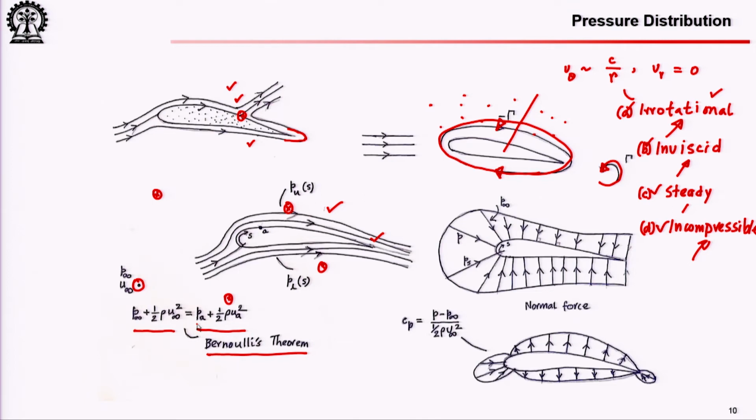These four assumptions can hold if the flight speed satisfies that incompressible range. As I said in previous lectures, if you go into the compressible range, either you have to use some correction, you can still obtain your results from application of this, but you have to fit in some compressibility corrections, or you can straight away use the compressible pressure stagnation pressure relationship, which I gave you: P naught by P equals 1 plus gamma minus 1 by 2 Mach number square, to the power gamma by gamma minus 1.